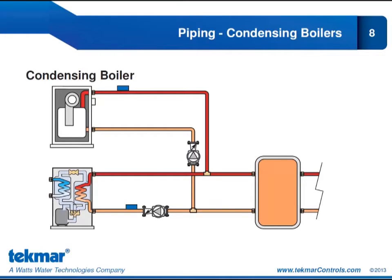So on the heat pump side of the tank, this is where we're going to see our lowest return water temperature. So we can have those lowest temperatures come up to our boiler. We can have the condensing operation to get those higher efficiencies. And then that higher temperature water will come back onto the supply side of the heat pump over to our tank. So we pipe it in this way because we want to ensure that we are operating our condensing boiler so that we take advantage of those higher efficiencies.